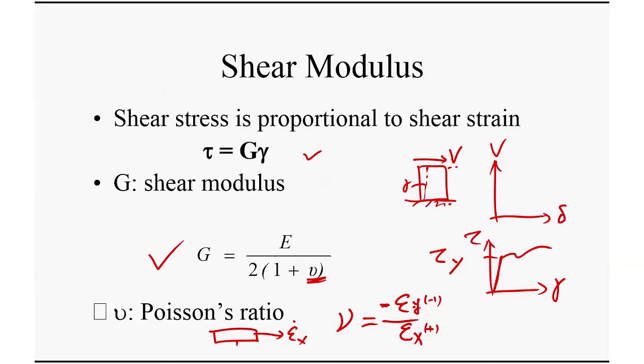And for most materials, this changes within a range. We're going to discuss in chapter 7 the range of Poisson's ratio. But for most materials, it's from 0 to 0.5. That's the range. And what's 0.5? 0.5 is like for tissue, for muscle, for things that do not change volume when you stretch them. They keep a constant volume, and then the Poisson's ratio is 0.5. And there's a section here that I leave for you. It's very fun to read, so read the textbook.